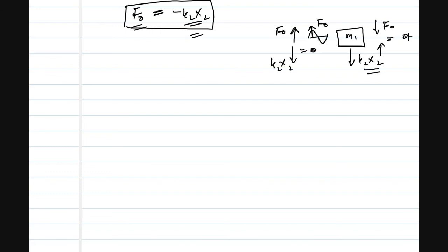I'm again repeating, whenever you install a mass spring system to a main mass such that the excitation frequency coming from the external source becomes equal to the individual natural frequency of k2 and m2, then your x1 goes to 0. The amplitude of the main mass, which was vibrating before, goes to 0, but m2 gets some amplitude, which you can also control by properly designing the vibration absorber.